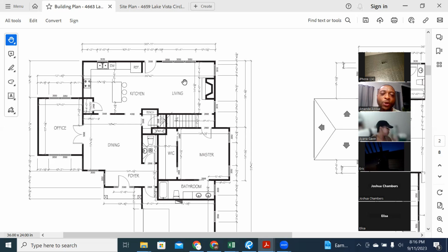No, we don't do a monolithic pour for a wall. We get the inspection passed, and then once we pass inspection, we pour the footings. When we pour the footings, we're going to stick in some rebar, some high rebar. You'll see it in the video. You'll see some tall rebar. And then when that footing dries with the rebar sticking up, we're going to come back with the forms.